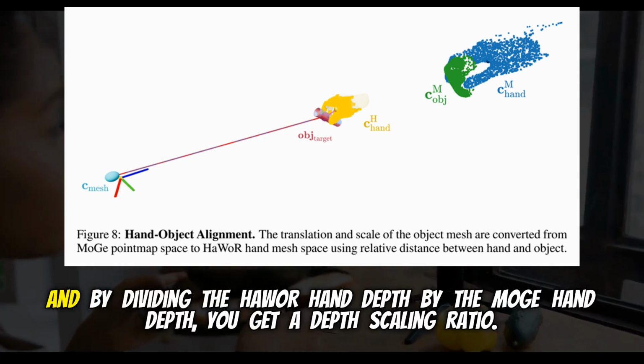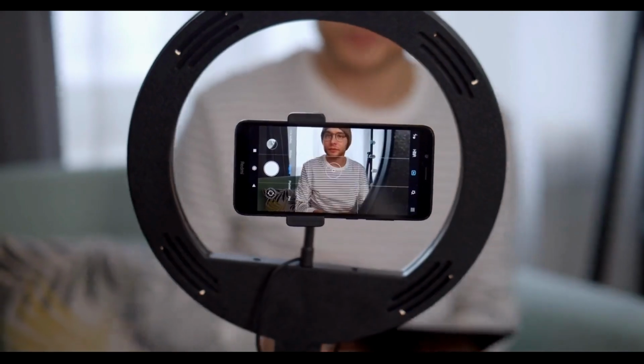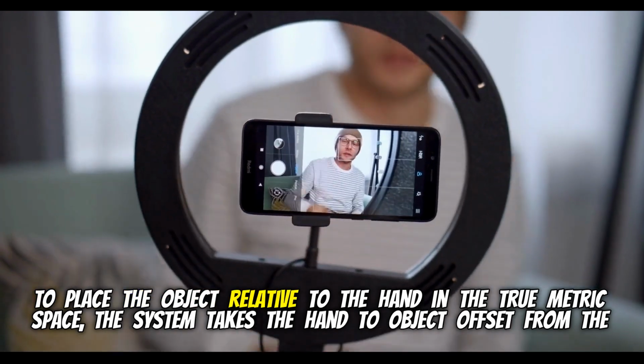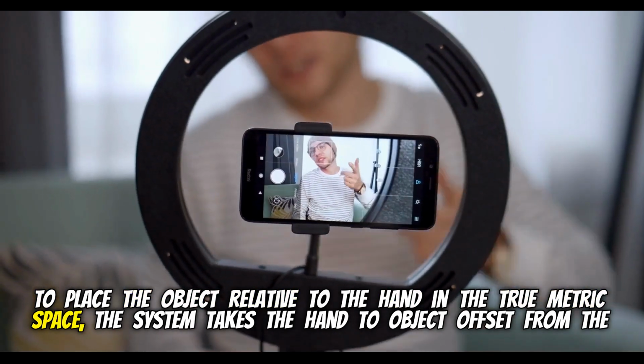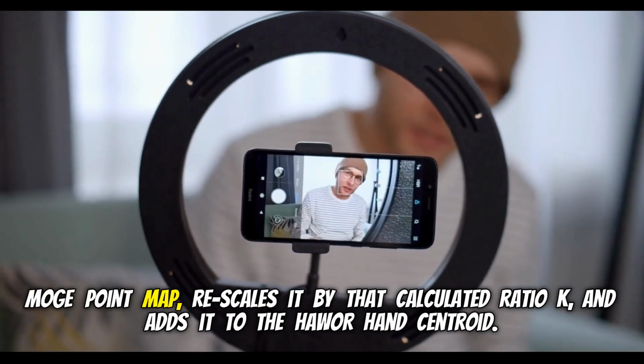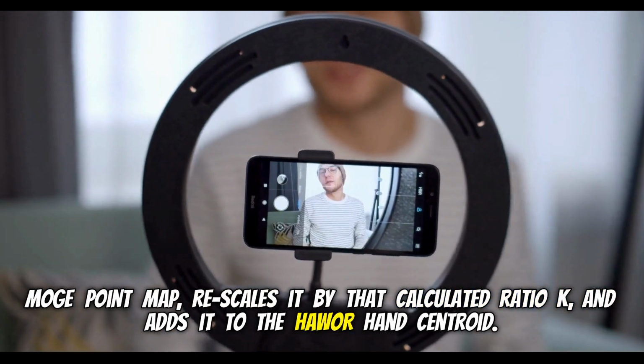You got it. Right. And by dividing the HaWoR hand depth by the Moog hand depth, you get a depth scaling ratio. Let's call it K. Okay, K, and then what? To place the object relative to the hand in the true metric space, the system takes the hand-to-object offset from the Moog point map, rescales it by that calculated ratio K, and adds it to the HaWoR hand centroid.